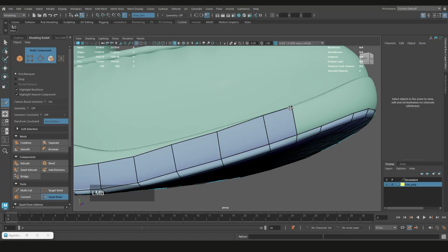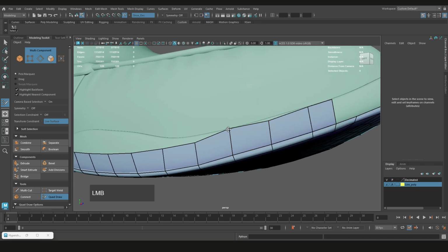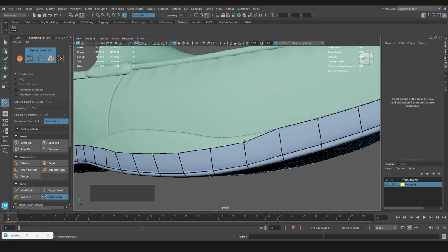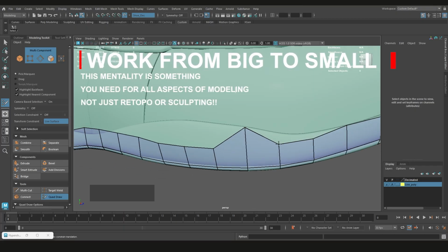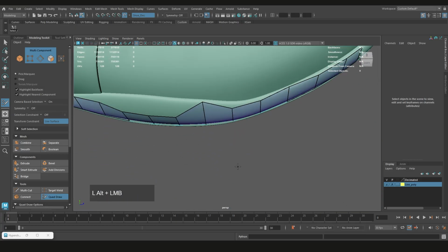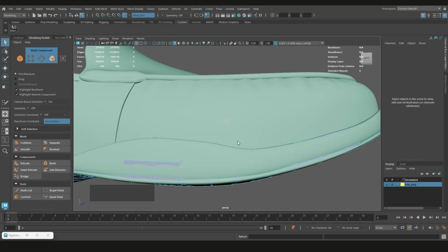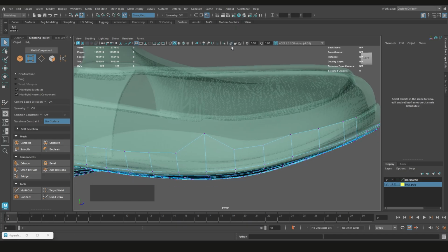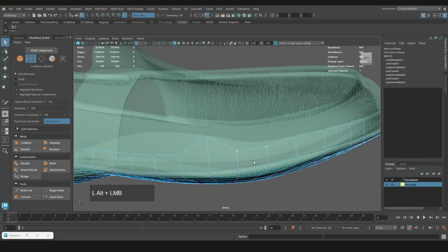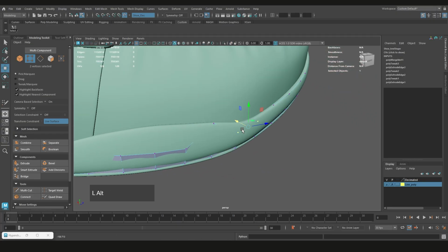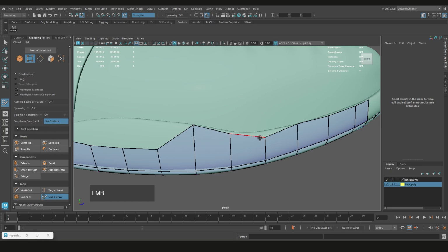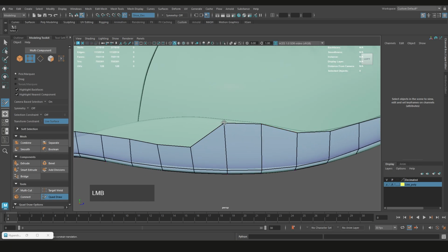So here what I'll do is I want another division here, so I'm going to Control click, but I just want to get this in here quickly, just so we know where it is, right? And here you can see it's already clipping edges there. So what I'll do is I'll press Q, go into vertex mode, and I have a shortcut for X-ray mode, and I can just select those two, press W, and then I'll just slide this out so it hits there again, and then Control Shift Q again to go back into that so we can actually grab these edges.